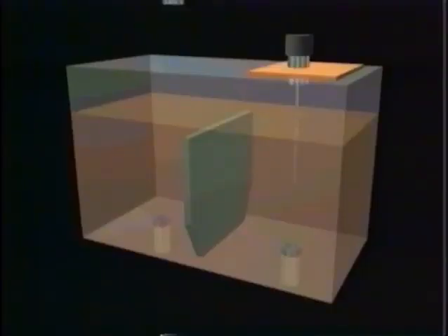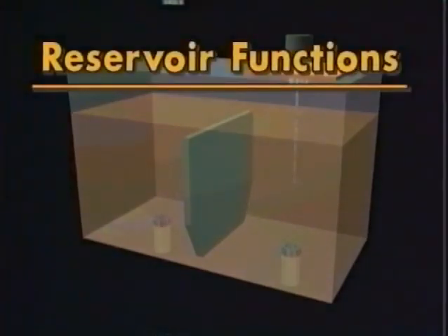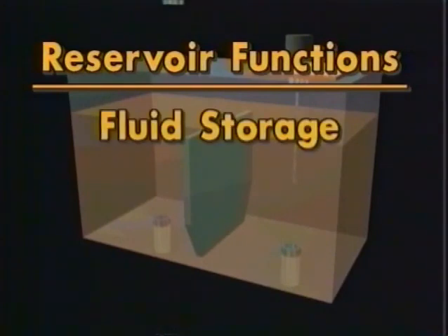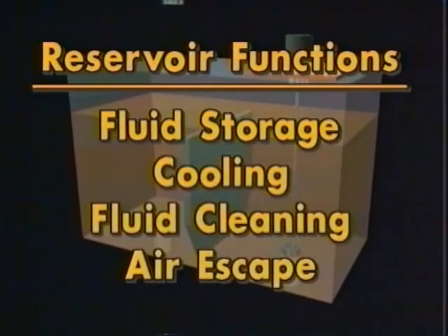The other principal component of a hydraulic system is the reservoir. The main purpose of the reservoir is to store excess hydraulic fluid. Other functions of the reservoir include cooling and cleaning the fluid and allowing air to escape from the system.